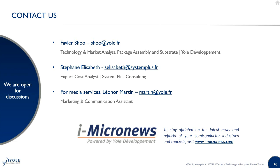Second question. Stefan, what is your opinion about the future of flip chip CSP? In this area, I think, like Javier, that we will see more and more fan-out applications in this field. As I mentioned before, the reliability of these components is critical. And as we have seen with Qualcomm, there's a total shift to the M series. I think we'll see more and more of this type of packaging in the future, replacing the traditional flip chip CSP.